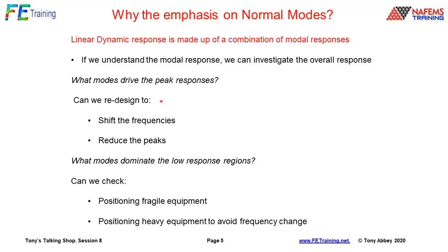And then if we think about design in general terms, can we shift the frequencies around? Well, what are the key frequencies? We can usually lower a frequency. Maybe we can increase the frequency by very carefully increasing the stiffness without increasing the mass. Tricky thing to do, but we might be able to do it.